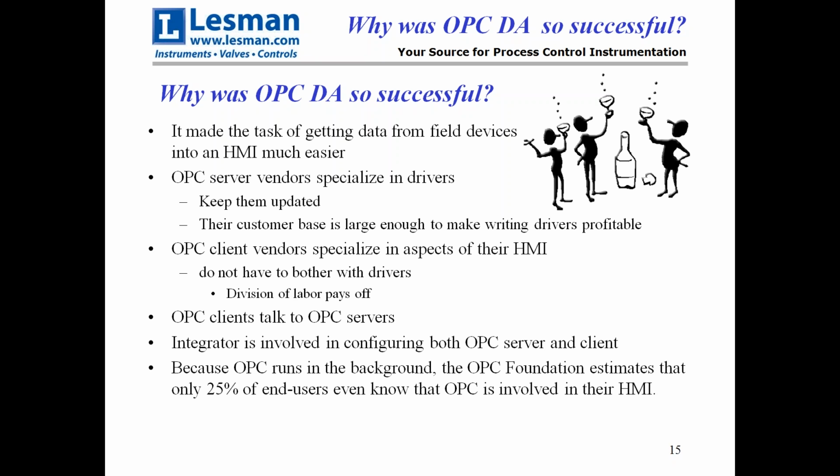It really works well to have OPC server people doing exactly what they do, because it makes it work really well. And it released the OPC client people from having to bother with the effort of having to talk to the instrument. All they're going to deal with is saying, hey, I want this data with this tag name, give it to me. Bonk, and it shows up, and it's already in the right format for them to deal with. So the integrator, again, gets involved in configuring both the OPC server and the OPC client. He's the poor guy that actually has to build the database inside these things that makes it work.